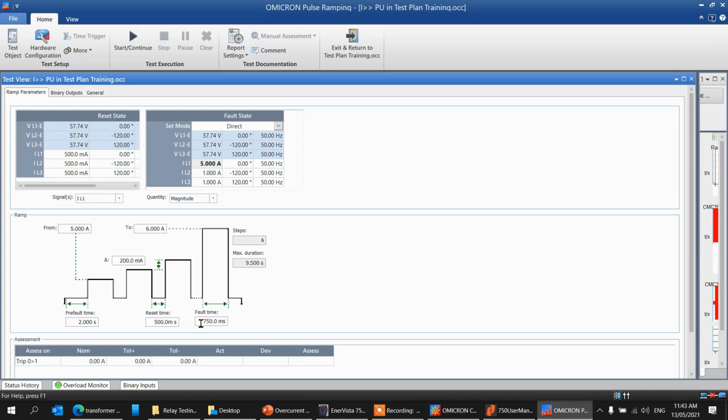What happened is there's a process inside the relay. Let's look if this is within the threshold or still not in the threshold. So every 75 milliseconds, it will stay there on that level with an increment, after that it will go to rest to avoid cooking the contact.